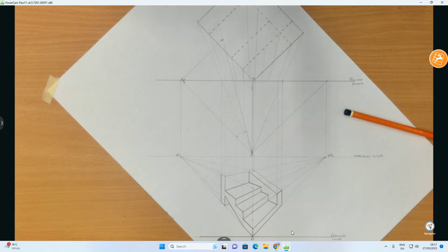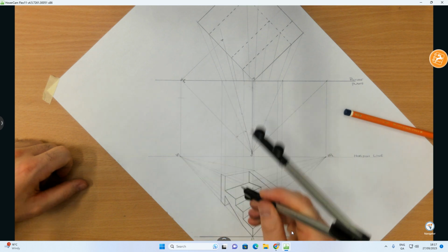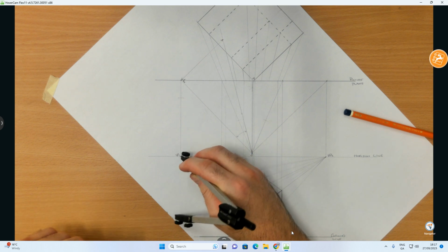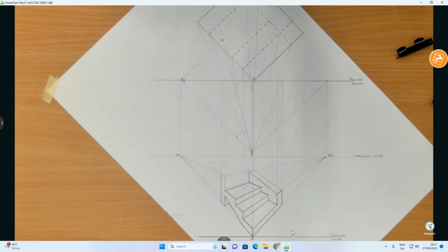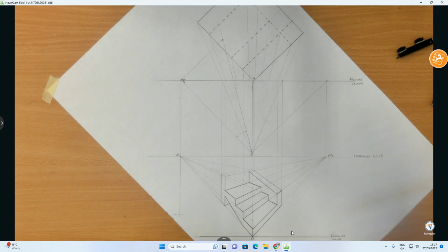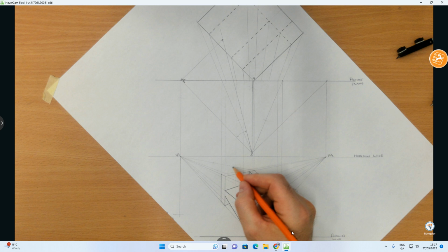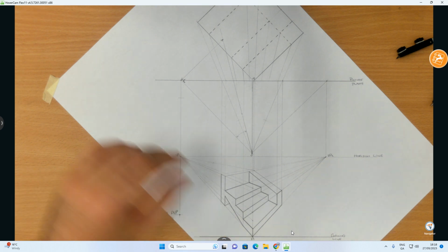on my compass, and from VP1, I'm going to do above. I'm just thinking which way is it going. It's actually going below the line. Apologies. So I'll do it down here. And all I need to do from VP1 is extend down. Depending on which direction, because my roof is going to be going up like this, that means I had to go below VP1. So this point right here, I'm going to call it AVP. AVP stands for auxiliary vanishing points.